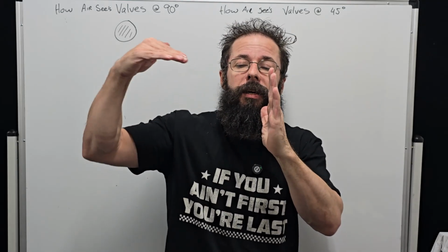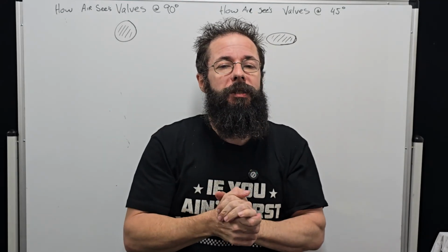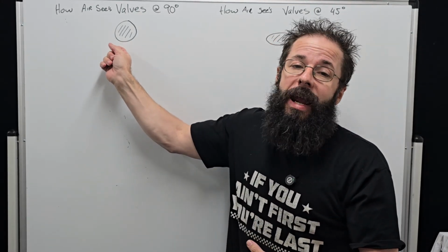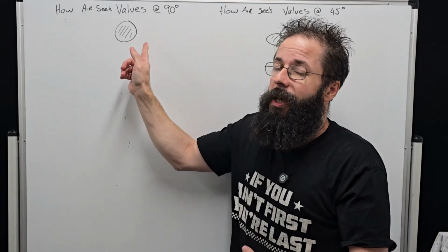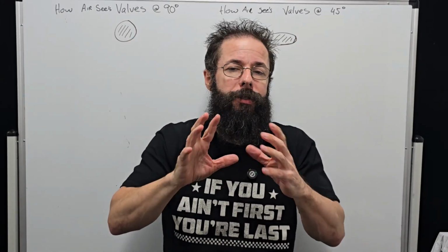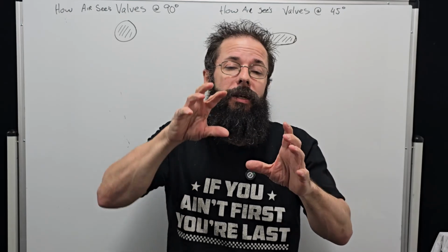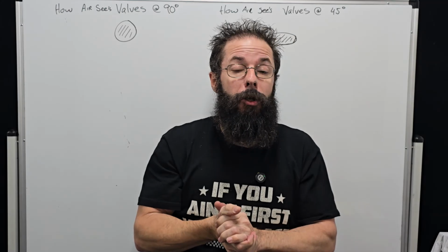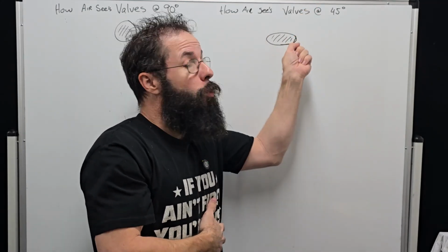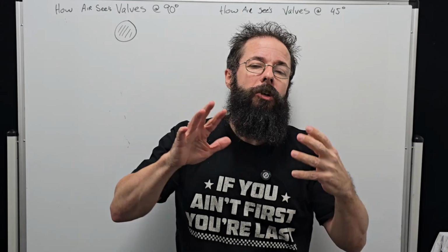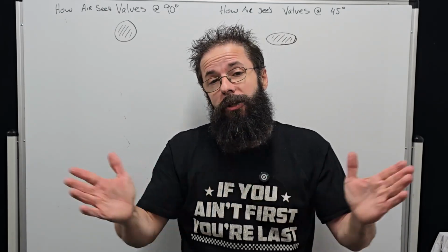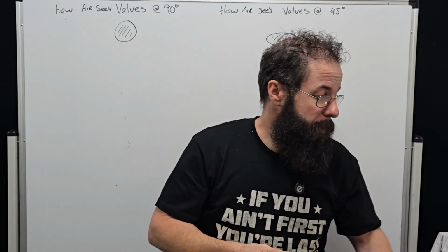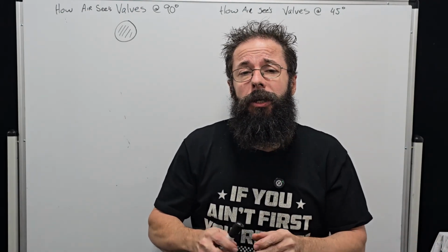So now if the air coming in and transitioning into the valve stem itself, it'll now see a nice oval versus a round object, which we're going to get a hell of a lot of eddies around. So this is why port velocity and also the gradient and angles are super critical when approaching a valve stem, because just by the approach angle, we can improve the aerodynamic shape of a valve stem, even though we're not changing the shape. Hopefully that makes sense. If it doesn't, put something in the comments and I'll break it down some more. But all right, so now we're going to go into